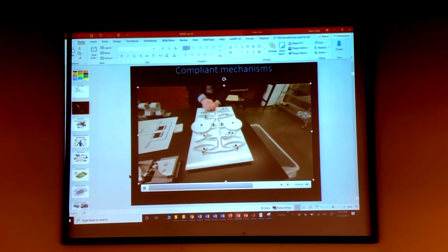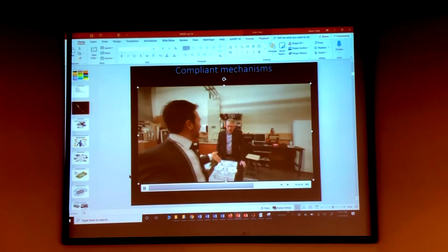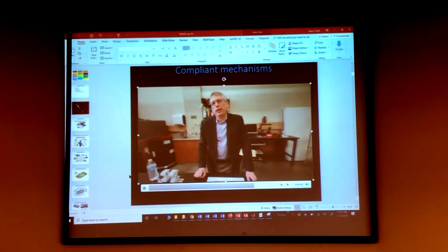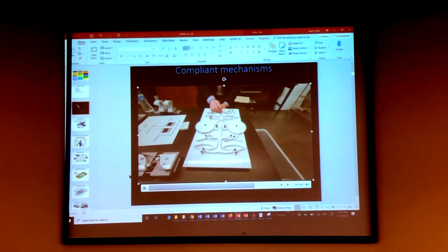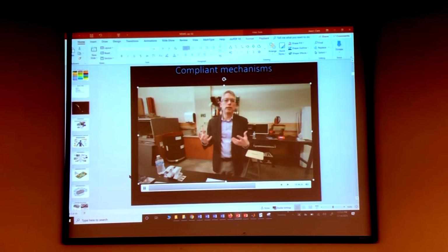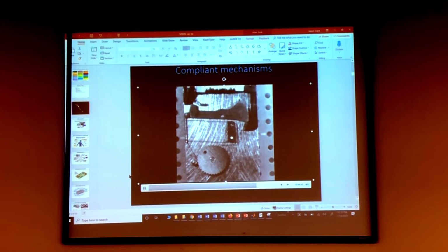Its purpose is to ensure that no random vibrations, say from an earthquake, inadvertently disable safeties and arm the nuclear weapon. Now, one of the requirements was that this device be made as small as possible. They had made those as small as they possibly could using traditional methods, even using things like what the Swiss watch manufacturers were using. With compliant mechanisms, they produced a device out of hardened stainless steel, where some components were the size of a human hair.